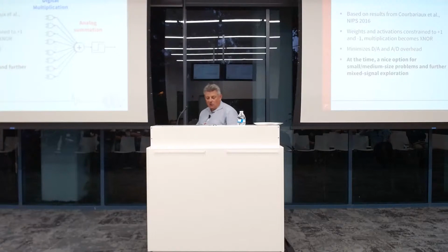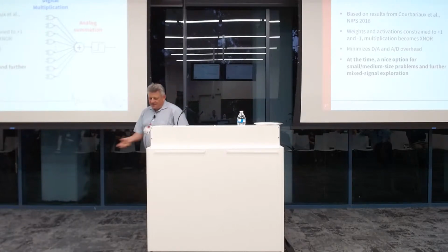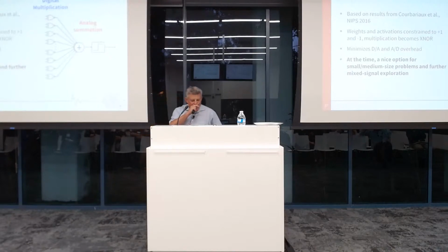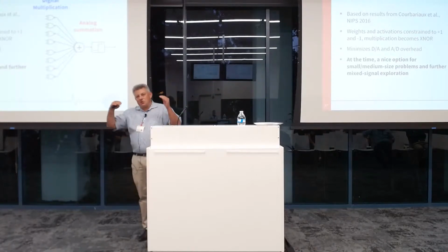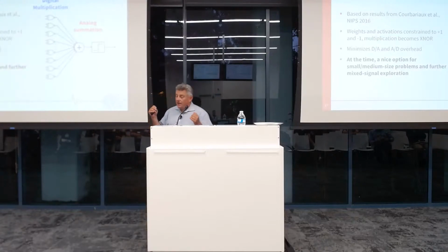So, you know, academics don't give up. So we continued. And we said, well, we learned something really important. You know, we got to cut out as much useless digital control signals as possible. We got to simplify the multipliers. We got to reduce the overhead. We got to reduce signal-independent switching activity. Exploit low activity factors of neural networks. There's actually not as much switching activity as you may think in a neural network. And so we came up with an architecture that kind of fits our fabric much better.